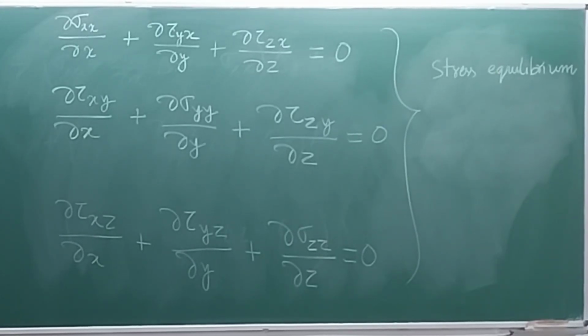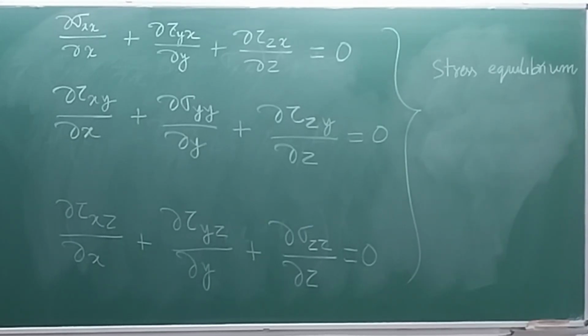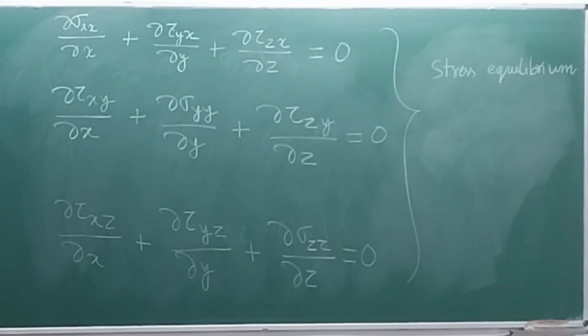How does it move? That is because of the internal viscosity. That is because of what is technically referred to as the diffusion of momentum. You have the top wall sliding, it drags the fluid attached to the adjacent layer. That layer in turn drags the next layer. So because of viscous forces, the momentum in the sliding wall gets transferred to the entire fluid. But this is not a body force.